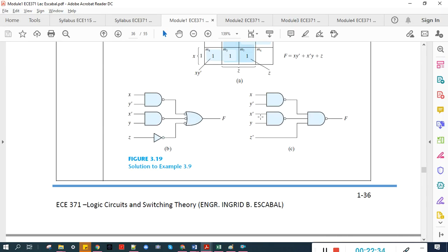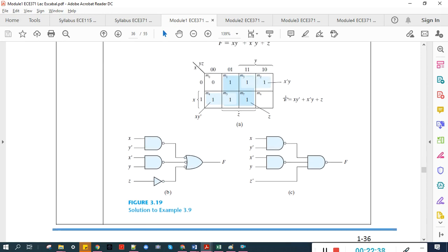See the pattern? Can you see now the pattern in implementing this? Just replace, this is ANDed, and you can use AND. This is ANDed, you use NAND gate for that. And this is ORed, you use a NOR gate, because these two bubbles here, they will just cancel out, so it's the same function as this one.